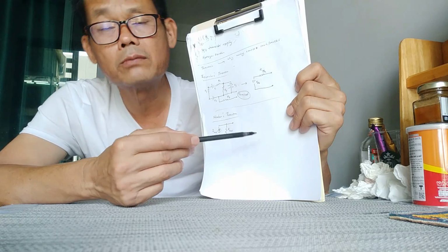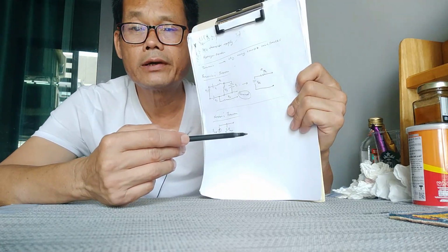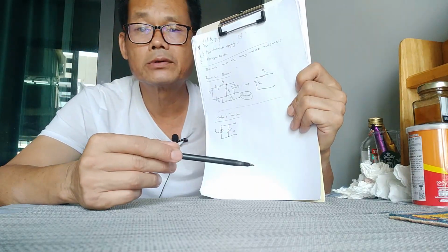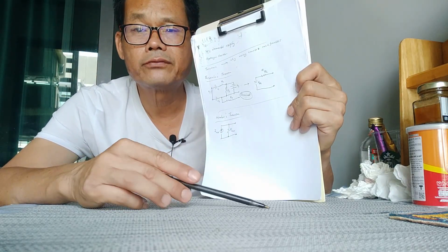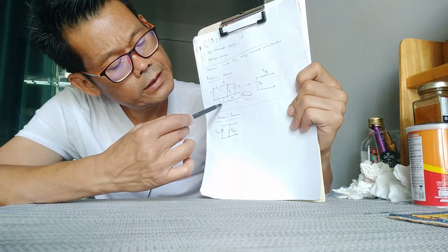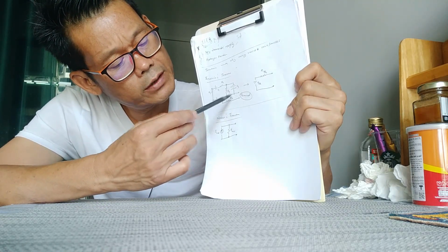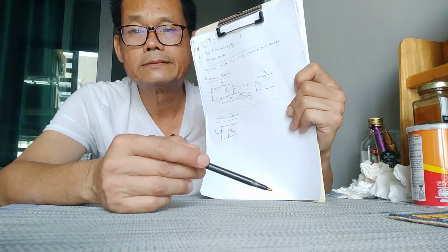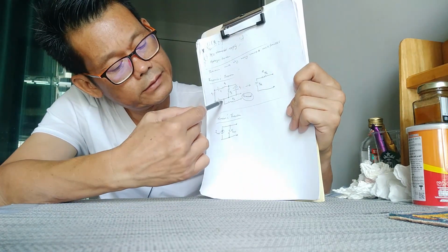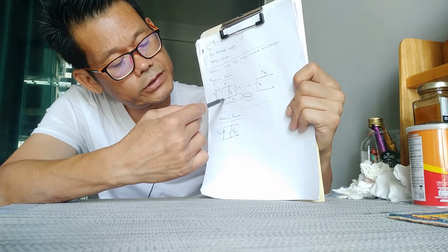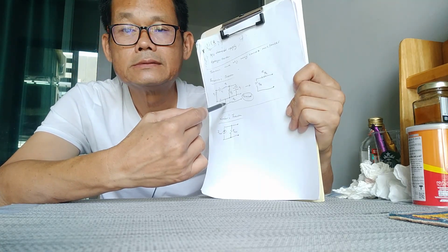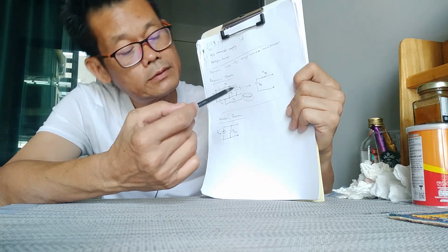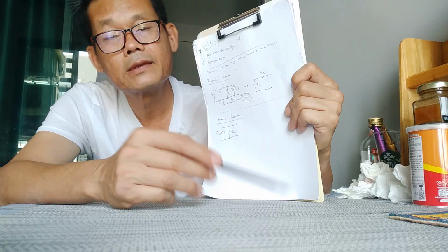By applying Ohm's law, delta V equals IR. When you have no current, because this is open circuit, your delta V has to be 0. If you put this one as V2 and this is V1, V2 is going to be equal to V1. That's what you're looking for, the voltage at this point. That becomes V open, or VTH, and you can put this right here.